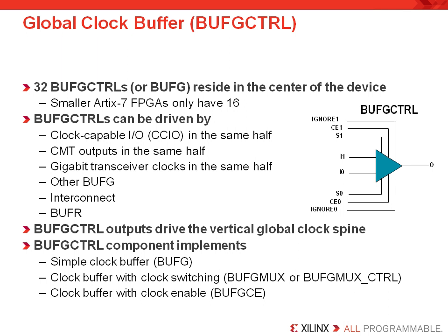Access to all clock routing networks is provided by clock buffers. Global clock networks are driven by the global clock buffer called the BUFG. The regional clock networks are driven by a regional clock buffer called the BUFR, and the I/O clock networks are driven by the I/O clock buffer called the BUFIO. Now, the basic buffer primitive that we're seeing here has variations on the basic buffer and provides additional functionality, including switching, muxing, gating, and clock division functionalities.